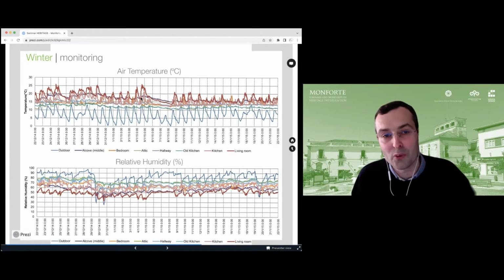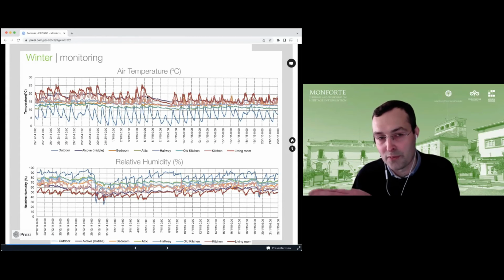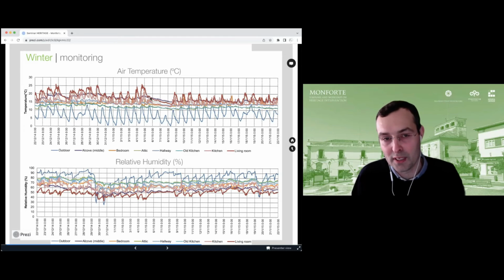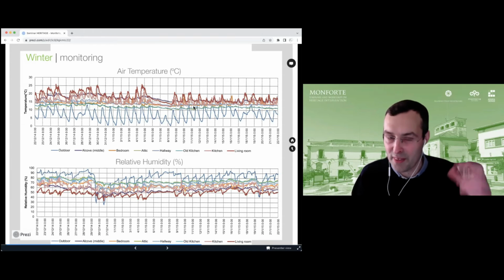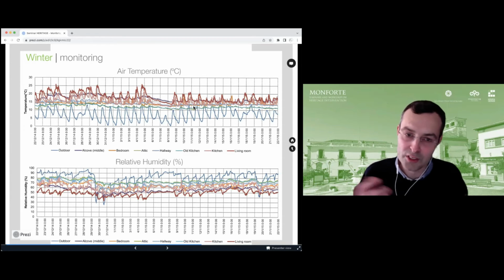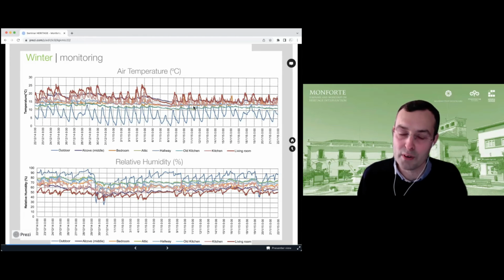But for example, when you have 2 days in a row where they were heating the building, when they left the building for a couple of days of vacations, the building takes almost 4 days to descend to the temperature of the other rooms. So the thermal inertia of the building also has a very relevant behavior on this topic.